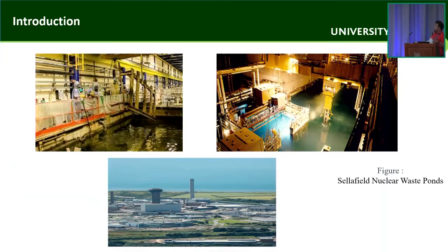This is a picture of the Sellafield nuclear waste pond. There is so much scope for work regarding clarifiers and hydraulic transport lines. Basically, these are among the most common unit types for primary separation of flocculated waste. Performance issues like the formation of strong inlet circulation currents that can increase the presence of solids in the outlet flow are key factors in design. So as a result, consideration of the industrial unit is significant, where CFD is often used to simulate this.